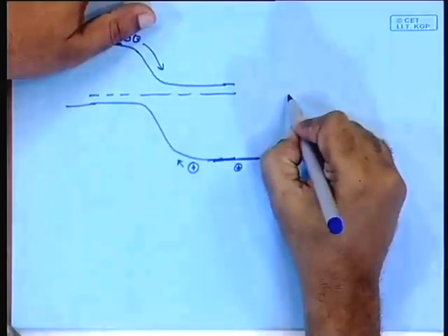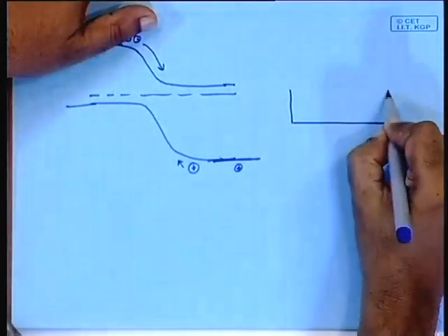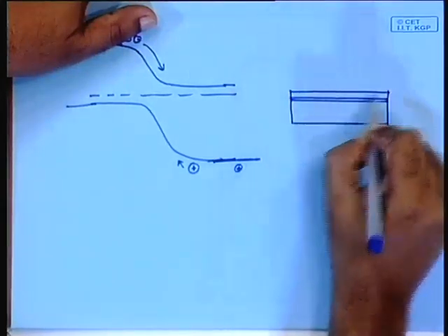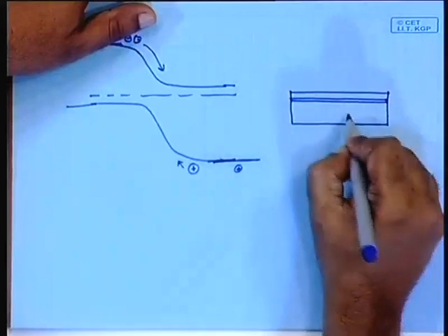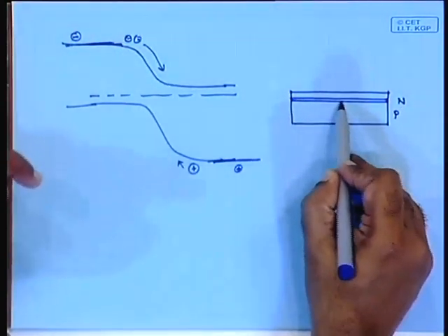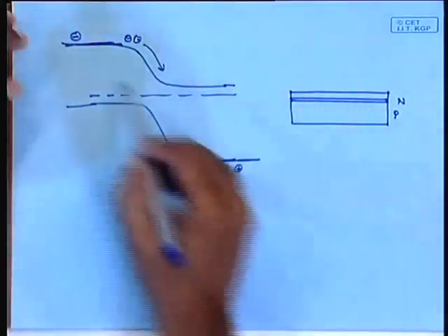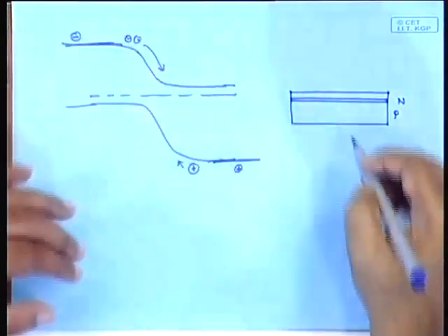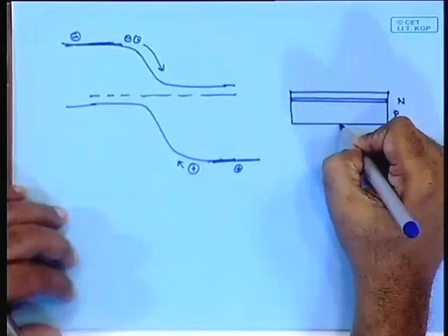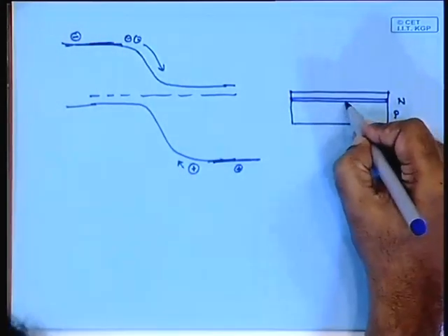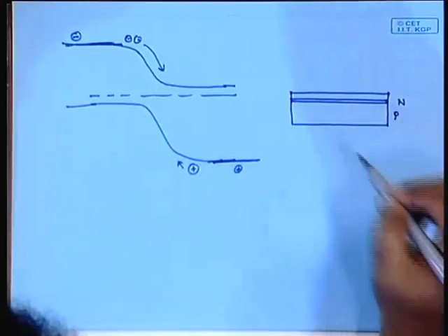Instead of, what you have learnt is that you will have a P layer and a thin N layer, and on top of that the metal contact. So, here is the P, here is the N. Now, this N side is anyway very thin, so it does not really matter, the electric field goes through the whole length, no problem, but here the P layer is large. If the P layer is thick, you cannot have the whole electric field going into the whole P region.